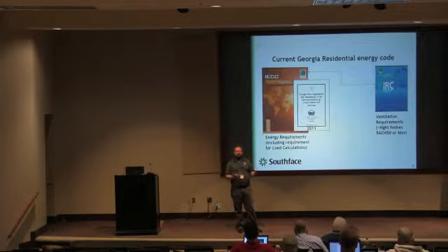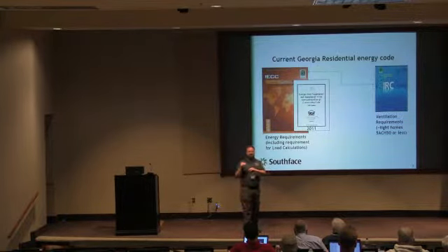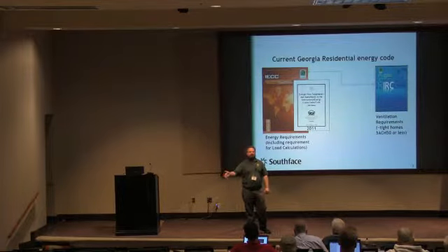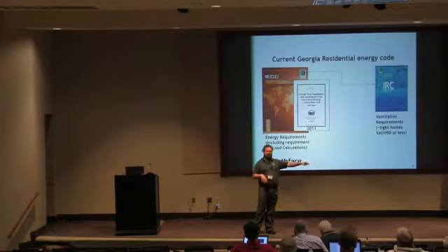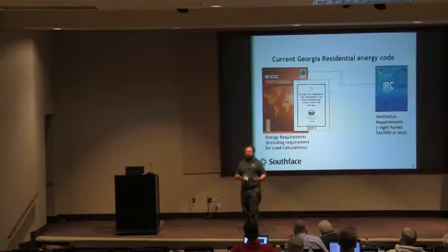And the reason we want to get ventilation in all homes is it's a really bad spot to be in right now, where you have to blower door test and you have to be less than 7, but if you're tighter than 5, you get penalized by having to add ventilation. We'd rather have everybody know they need to do ventilation up front, design and plan for it, rather than finding out at the end when it's going to be complex and expensive and may not even work particularly well. So that's kind of where we are now and a little bit of where we're going in the future.